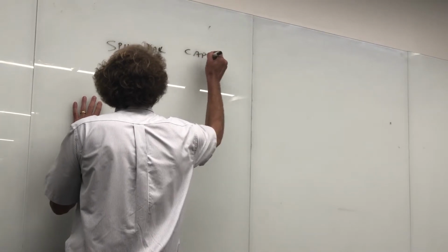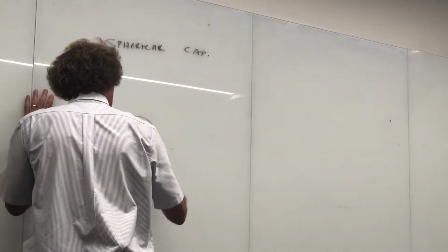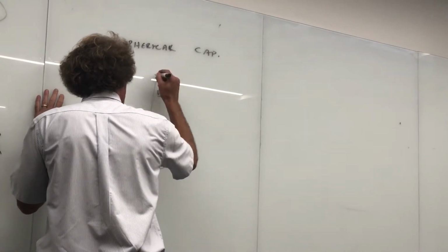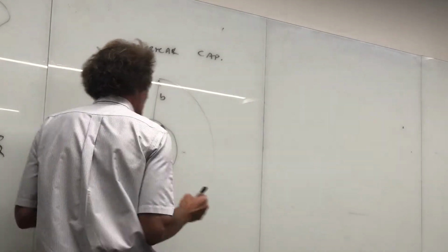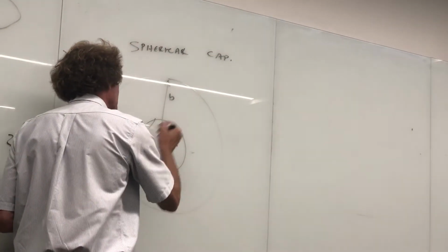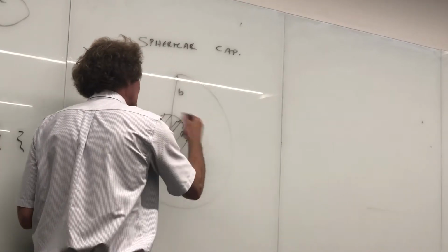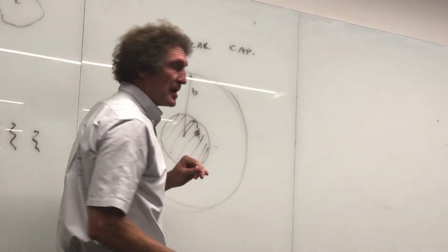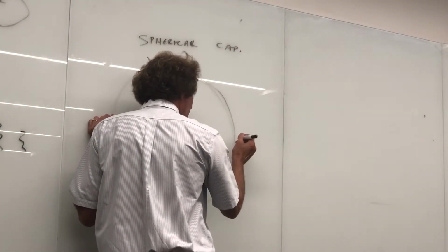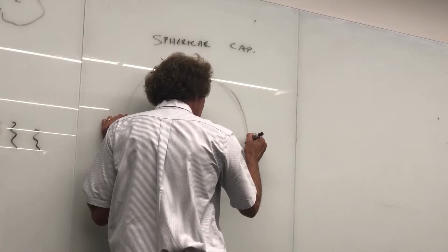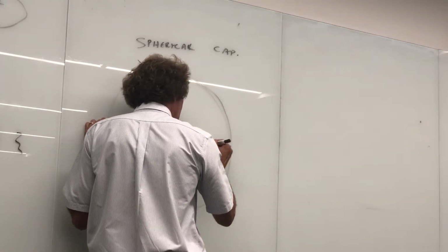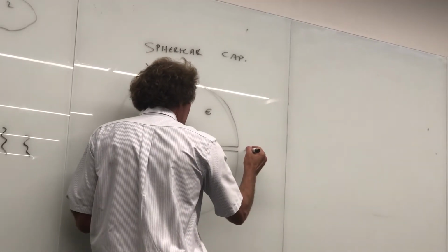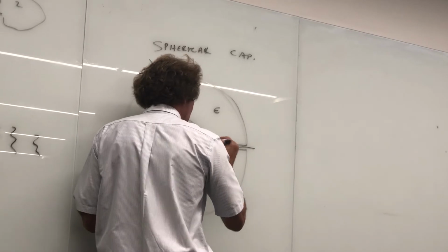spherical capacitor, what we do is we put an inner radius A, and then we put an outer radius B. We're going to assume that the inner thing is solid metal. It could be just metallized, and we're going to metallize the outer surface too, or make it a good conductor. And then we tunnel a hole, a small little hole through the dielectric. Remember, this has a dielectric epsilon between the plates. And we're going to run a wire right to this and connect it there.